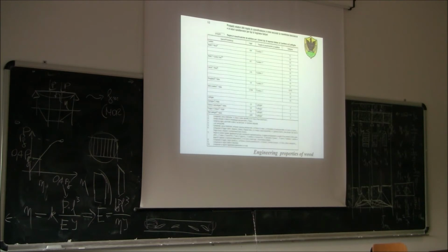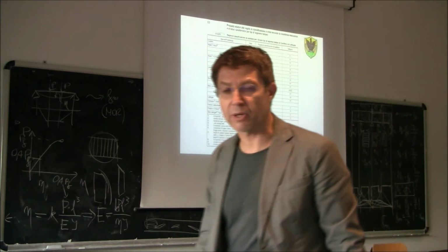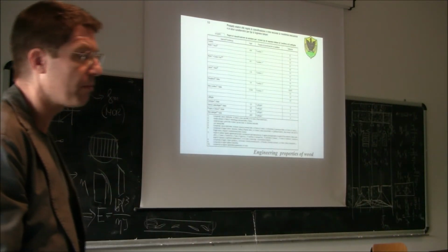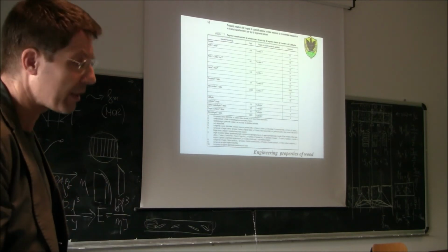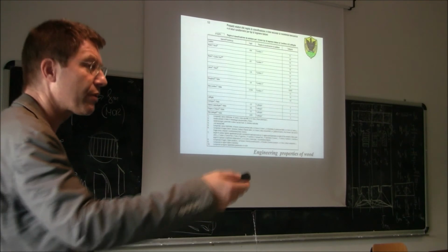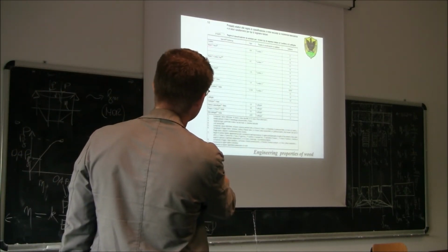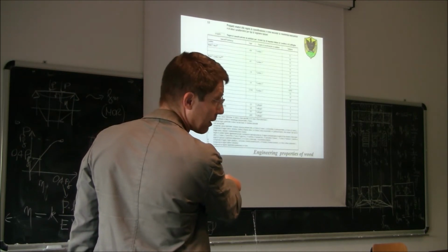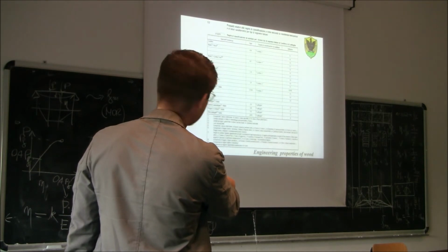So, let's have a look. This is the first table here. First of all, you need to understand which timber you are using and where it comes from. Suppose you bought spruce from Abruzzo. We don't have lots of spruce here, but assume that you have some spruce from Abruzzo. You go to this table: spruce, abete, nord, because we are centro-sud, abete, centro-sud. So spruce, Abruzzo is here.